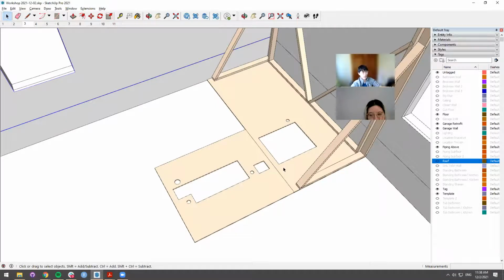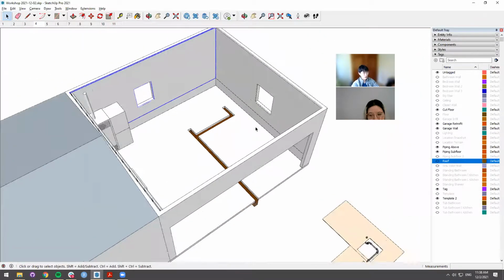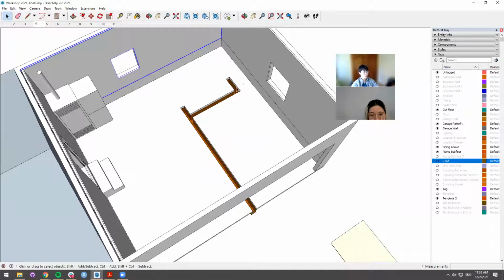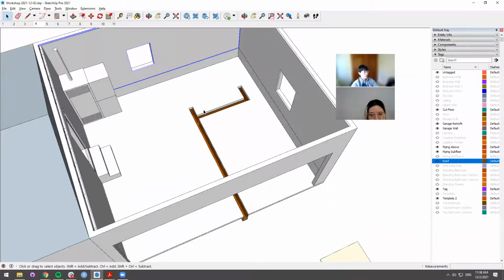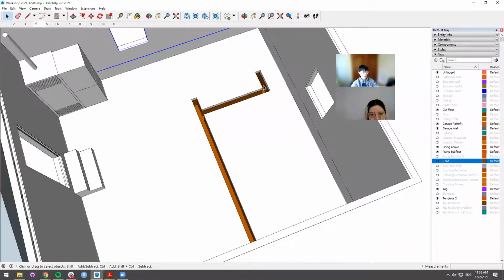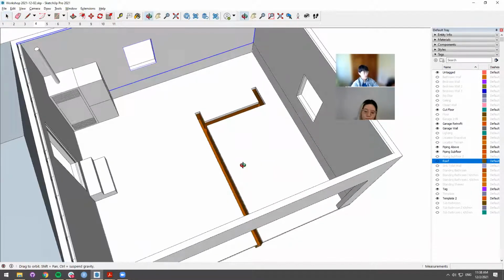The assumption here is that the lowest cost approach to dealing with subfloor plumbing is to do a trench like this inside of the garage. It can be even easier if you go out the right side. I'm just showing an example here if you needed to head to the main in this direction. This would allow you to preserve most of the concrete slab, and then you'll fill this back in after you've applied and added the subfloor plumbing.